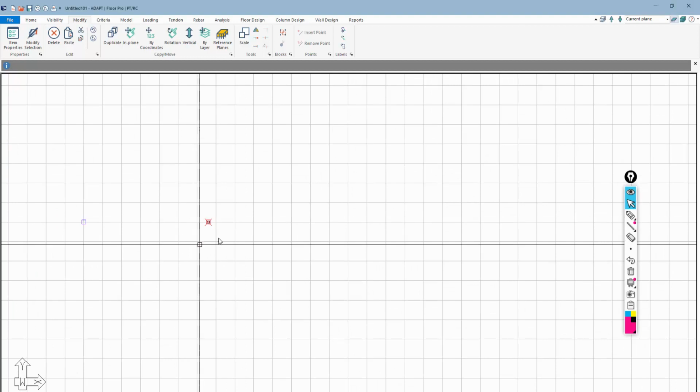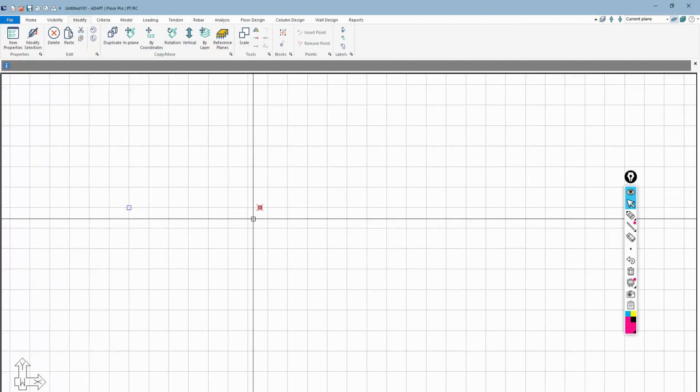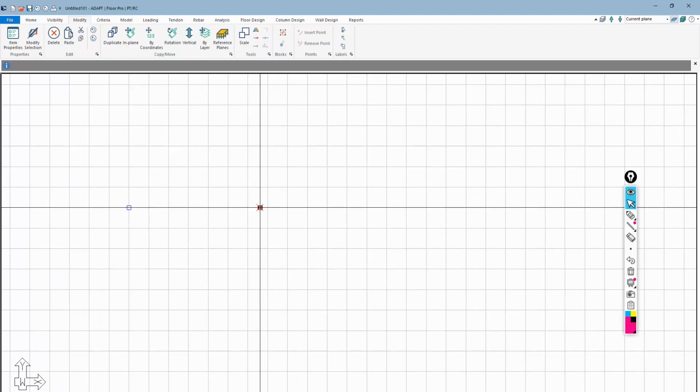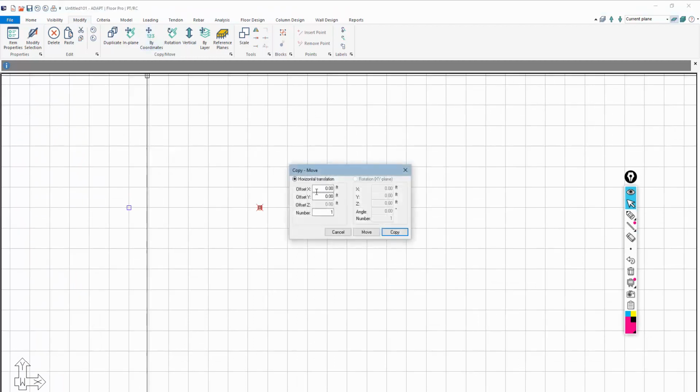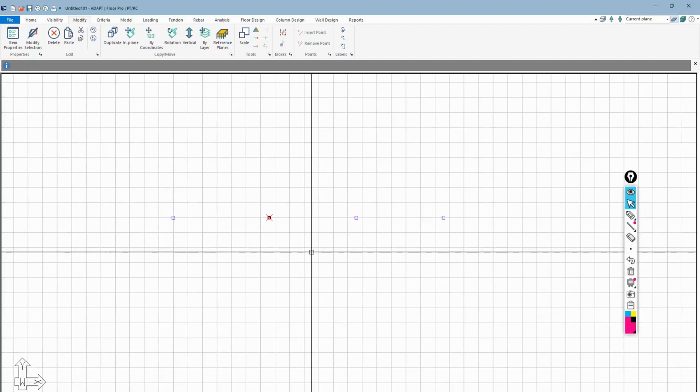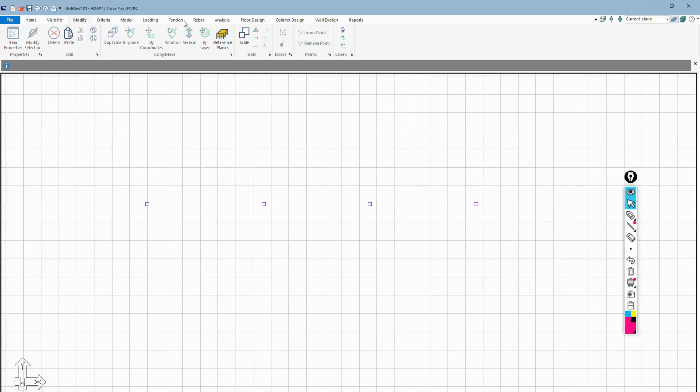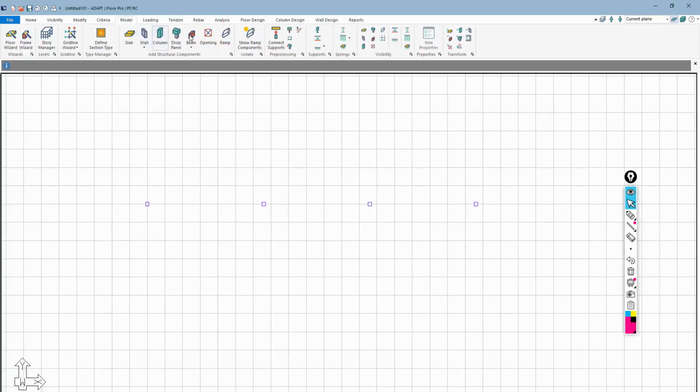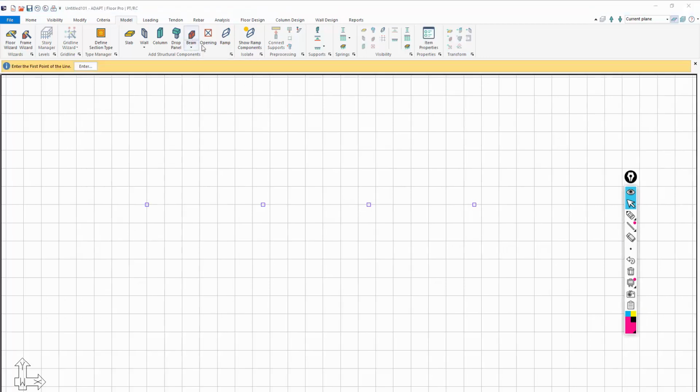So these grids really did not offer us much help. They will offer us a little help with the flange. We'll make it useful for the flange when we go ahead and model that. This column we're going to replicate 2 times at a 60-foot spacing. So we'll copy those over, and now what we'll do is just model the beams. So the beams by default are actually going to be flush with the current plane at the top.